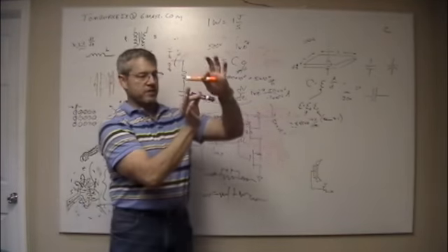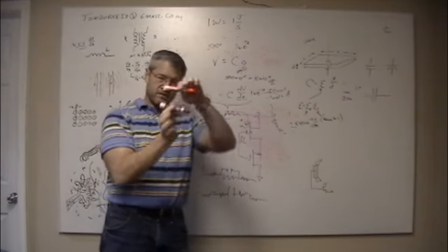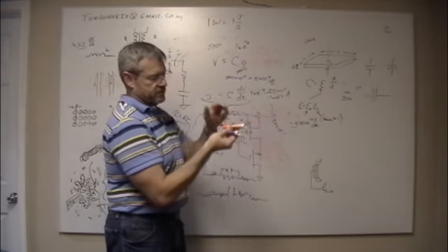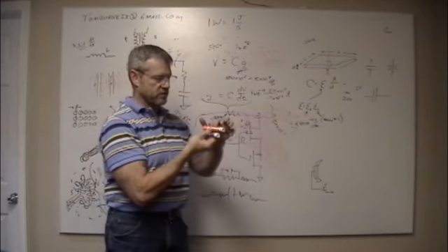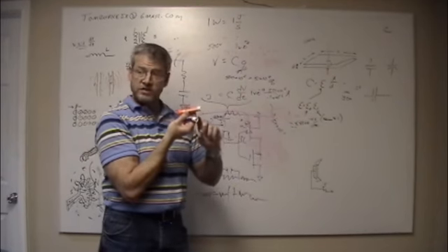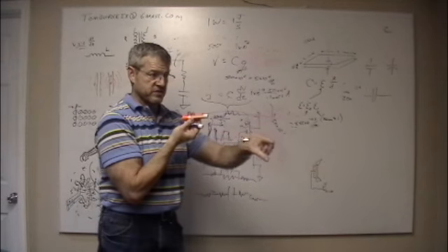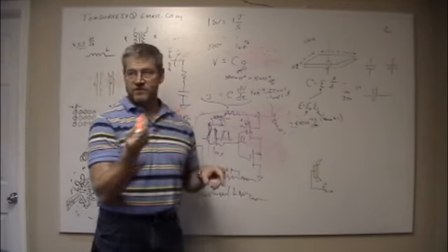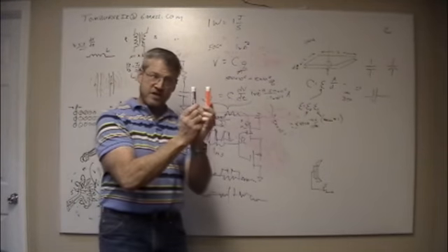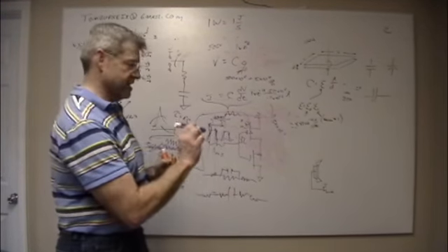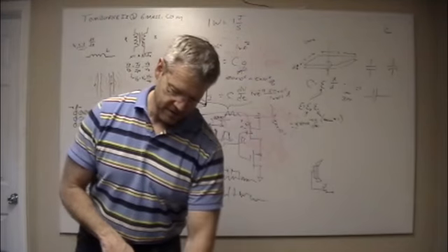Two wires is still two plates. There's some area there. And so when something starts wiggling on this wire, when you start throwing a square wave down this wire, some of it's going to crosstalk onto this one, and it's going to induce a signal over here. It's called capacitive coupling, as opposed to inductive. There's also some inductive coupling there too, but in this particular case, capacitive coupling.